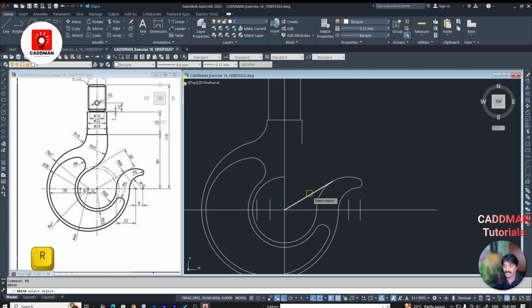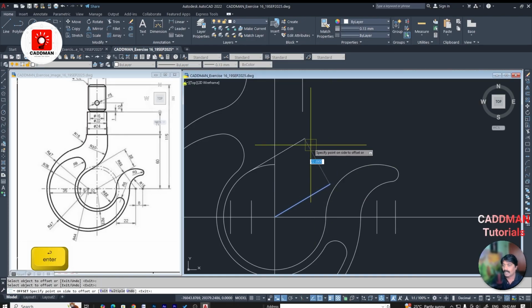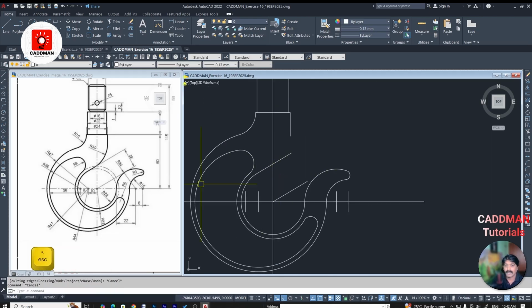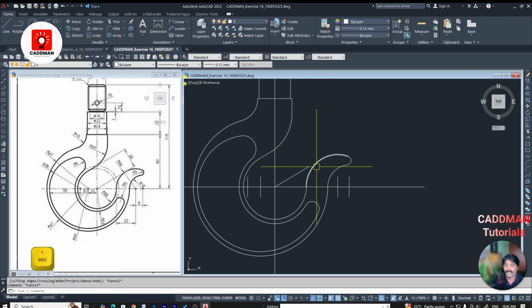now you got a line. I'll just try to break this off in order to keep this as my construction line. So I'll just try to, okay, construction line offset to 22. I got a line here. So to this line, I wanted to make a radius arc connecting these two lines and an arc between them. So fillet radius 30. I got my required profile.